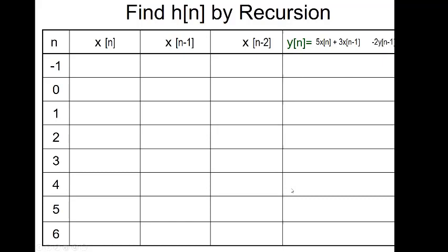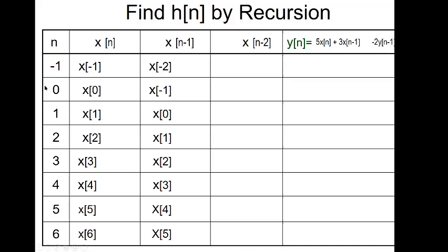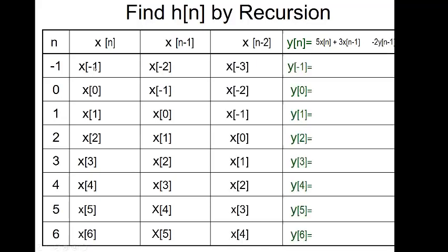We'll need a column to compute our output for those. We'll put our difference equation in here for the computation. We'll start just before n equals 0, when we start our unit sample sequence. And just so we see what's where, you don't need to write these indices into your tables. That'll take quite a while, but just to remind us that here x sub n at index 0, that's our x sub 0 term, and so on. So just to give me some locators here.